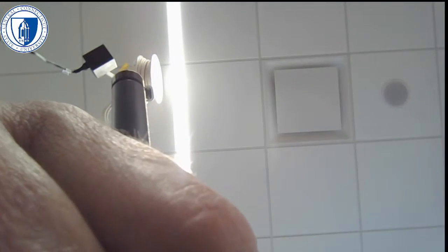Right, so this one to me just looks like a current divider, and the trick is we've got to get our ZL, right? So ZL is J omega L. Omega in this case is 25, and 600 millihenries, so it's 0.6.